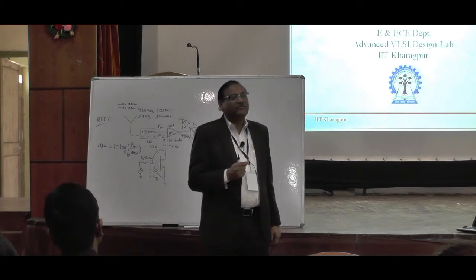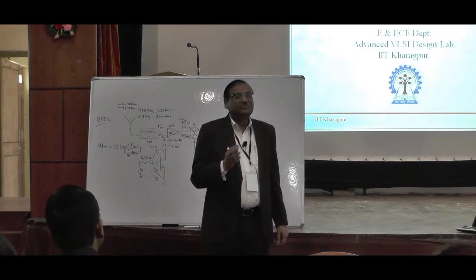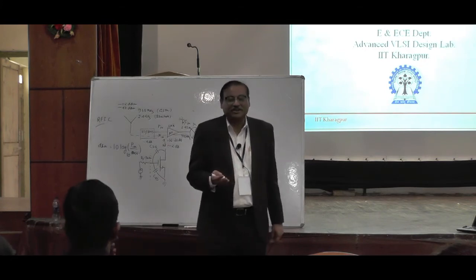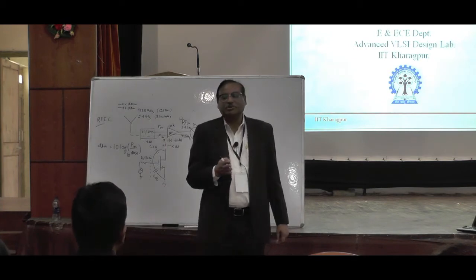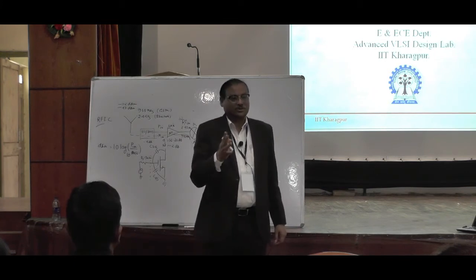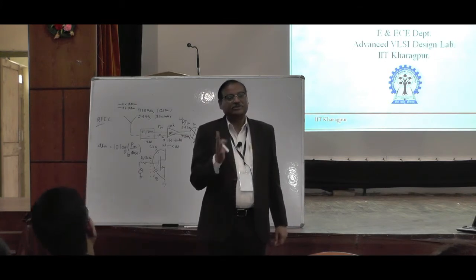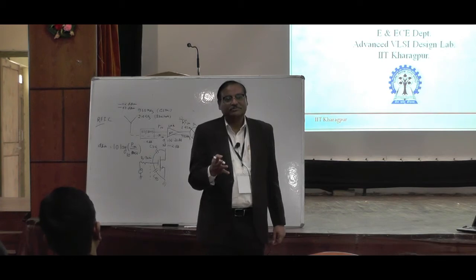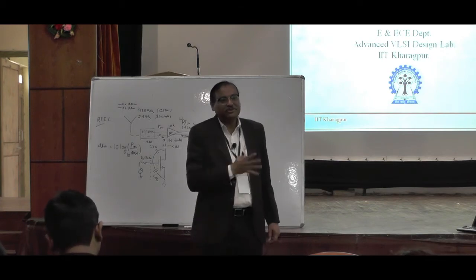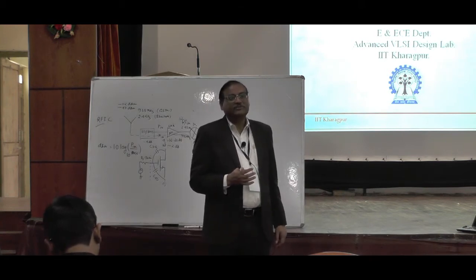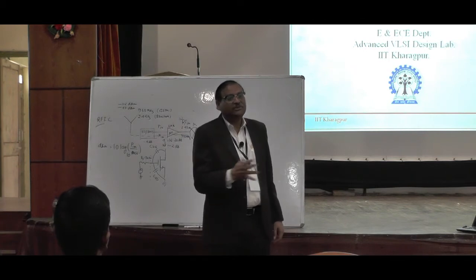That is the point where the microwave engineers, two decades ago when RFIC design started, even when we started, the conventional microwave people always said that none of your devices will work because you are not obeying the Maxwell equations. You are trying to solve by standard small signal analysis based on Kirchhoff's current and voltage laws. This is the problem, because a resistive source is feeding a purely reactive load, and the signal will not be maximally transferred. So it will be reflected.